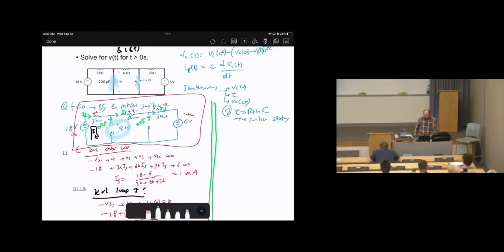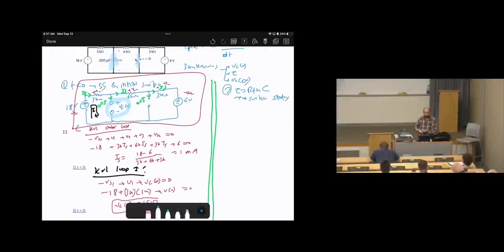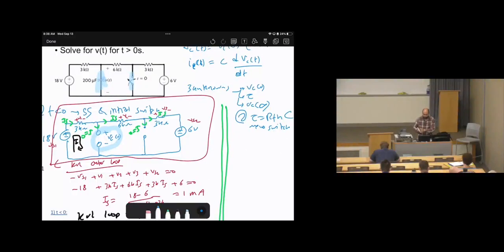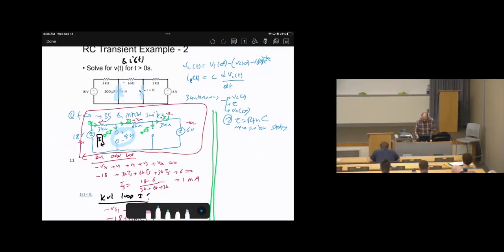Yes. So in every step, you treat the capacitor as an open circuit. Yes, you can say like this, right? But in step 2, finding R Thevenin, we are not treating the capacitor as an open circuit. We are calculating R Thevenin across the capacitor terminals, which is very similar to open circuit, yes. But technically, we cannot say open circuit. It is treated like this because we are removing this device and calculating R Thevenin across it. Okay. Now let's apply the new switch status, turn off the sources.